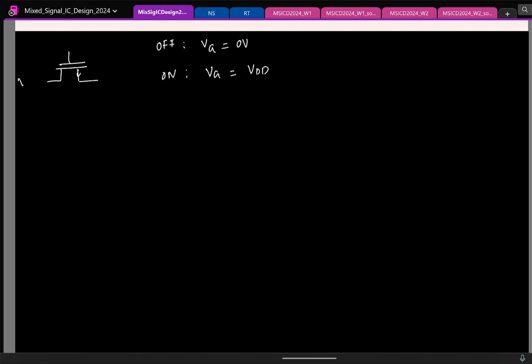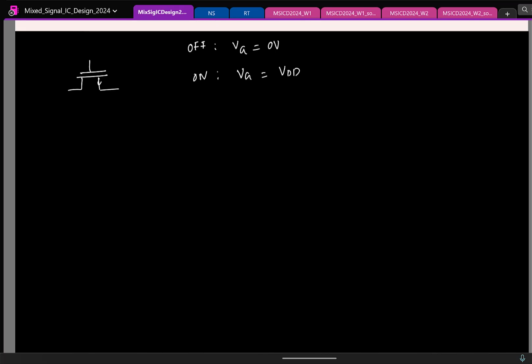So let's say this is V in. Make some space. So this is the sampling capacitor. I applied VDD. What do you get here at the output? Yeah, last class someone mentioned this is VDD minus VTH. I brushed up quickly, but why did this come about? Do you think for some case this can reach only till VDD minus VTH?